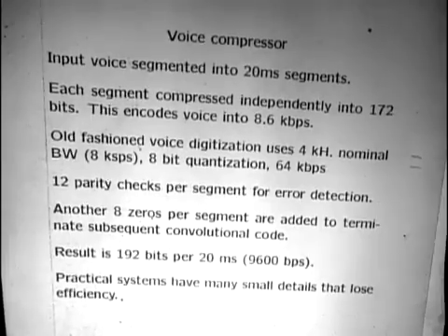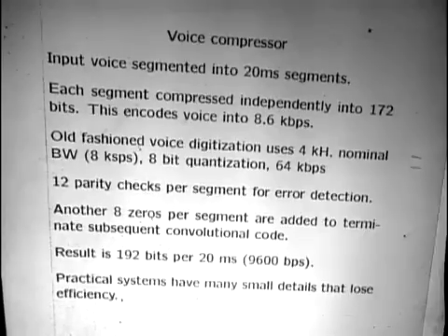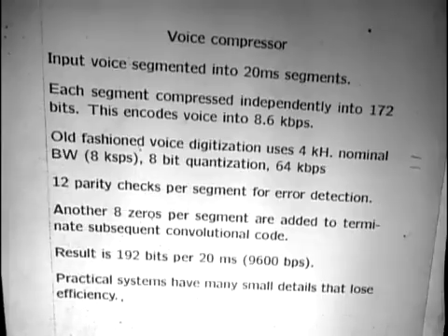Well, it sort of seems like it's probably a number that somebody picked out of a hat, but it's kind of striking that all of the standards use the same interval. And if you think about it a while, and I'll talk about this more on the next slide, the reason for this interval is that in voice communication, delay is enormously important. You don't want to have much delay. And since you don't want to have much delay, you have to do encoding over very, very short segments.